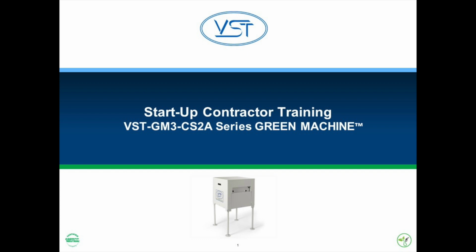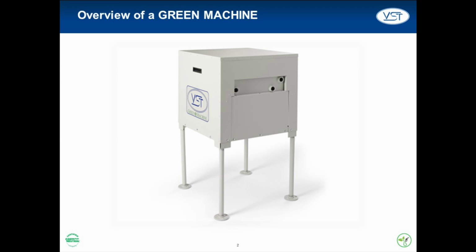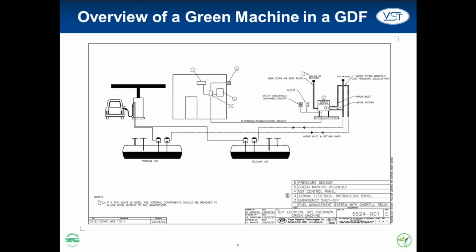But before we begin, here's a quick overview of the Green Machine. The Green Machine allows a GDF to capture, control, and monitor fugitive emissions to improve air and water quality. In short, when the Green Machine turns on, it pulls a vacuum on the underground storage tanks and pushes this hydrocarbon-infused vapor through an advanced filtration system. The air that comes out on the other side of the filter is clean air, and it is vented to the atmosphere. The hydrocarbons that were filtered out are then returned to the underground storage tank.